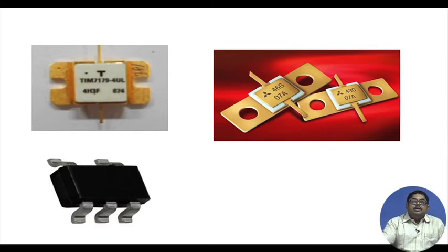I think with that we end this course, where we have mainly seen the various microwave technologies and some building blocks, particularly on the transmission side: how to model the whole transmission system, and the key concepts in waves, particularly the mode concept. What are the basic modes? Then we saw how, with knowledge of the modes, you can analyze how microwave signals propagate in various transmission structures.